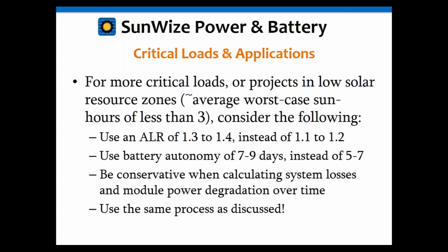Okay, I just want to again reiterate some of the most important things about sizing. Again, you want to make certain that you're conservative in your design. Again, better to be slightly oversized than to be undersized. You want to make certain that you have as accurate load data as possible. You want to try to go with as accurate solar insolation data as you have. If you're not certain, again, go to the lower one. Always better to go to the worst case scenario.